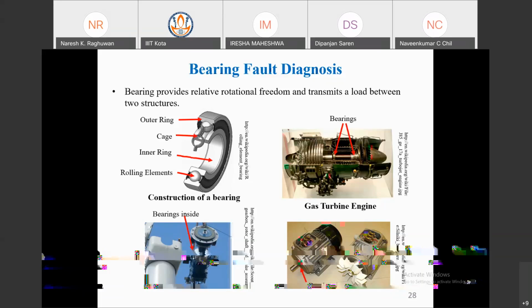For heavy loading, you can use the journal bearing. But in normal cases, with slight loading, in some gearboxes where the shaft is small, some ball bearings are there. So the failure of the ball bearing is very critical. You can see the figure, and I will explain something about this if you know the terminology of the bearing.